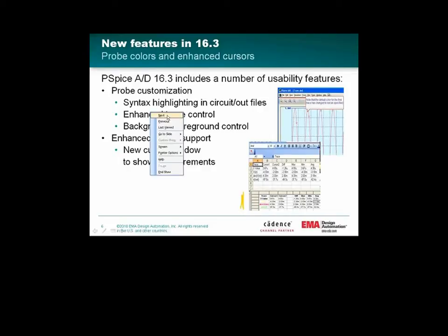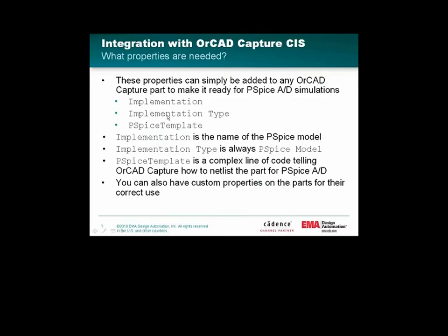See if I can get my next slide here. There we go. For those of you that are using CIS with Capture, some of you are. If you don't know what CIS is, it's not really that important. You can just ignore this slide. But for those that are using CIS, I just wanted to give you a little note on how you can actually use CIS and your database to manage your PSpice information as well. If you're using CIS, you're probably using it to manage your symbols and your footprints and all your part data. But you can actually use it to manage your PSpice information as well.